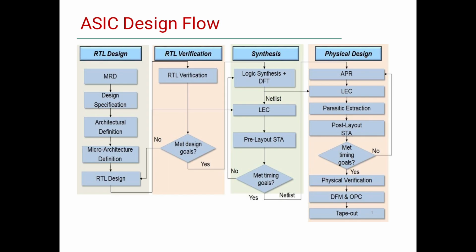microarchitecture definition. Next, RTL design, register transfer level designing using any language: Verilog, SystemVerilog, VHDL, any language can be used. Finally, it goes under verification. If it meets the code, the next process, logic synthesis, will be done, along with DFT, design for testability. Next, layout versus schematic, netlist. Netlist is nothing but the interconnections and gates that we are using.